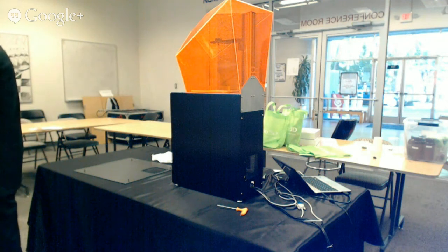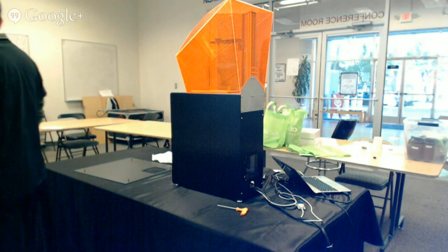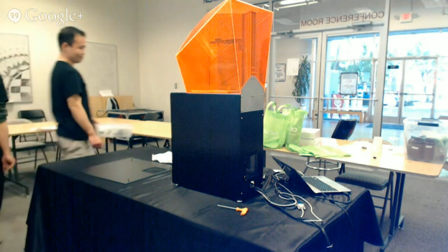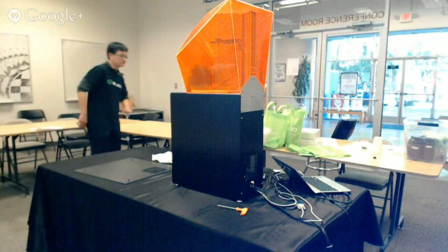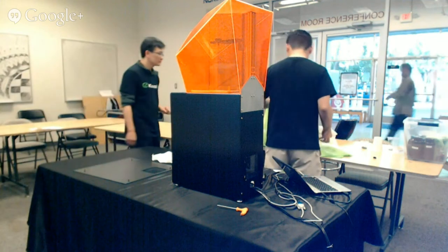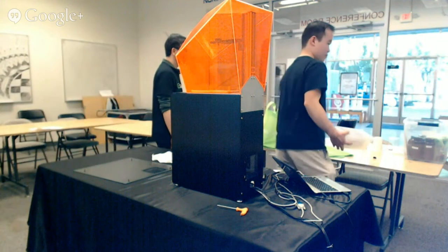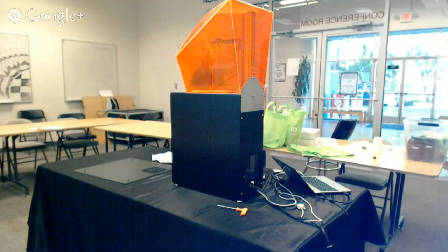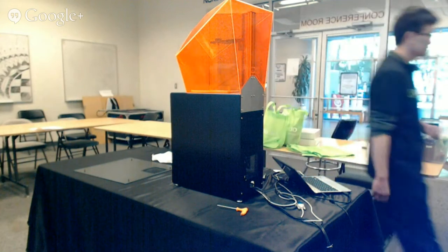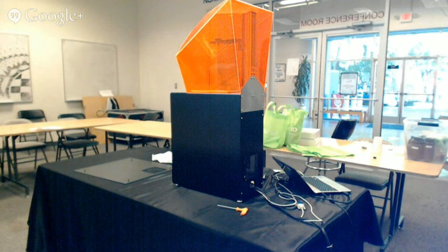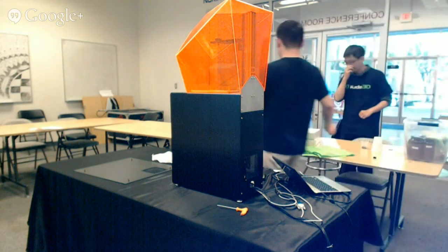Yeah, because photoinitiator itself is an inhibitor. So the chemical that initiates the polymerization itself absorbs UV and acts as an inhibitor. There was an interesting paper where they did tests about depth of cure versus speed of cure with different concentrations of initiator.